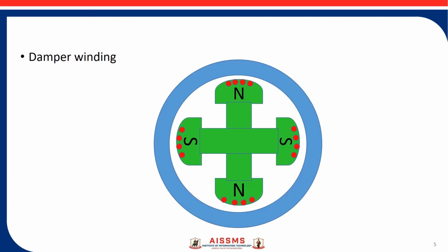we use damper winding. As you can see in the rotor pole shoes, we have included round conductors, and these round conductors are shorted at both ends. So this construction resembles squirrel cage induction motor, round conductors shorted at both ends with a ring.